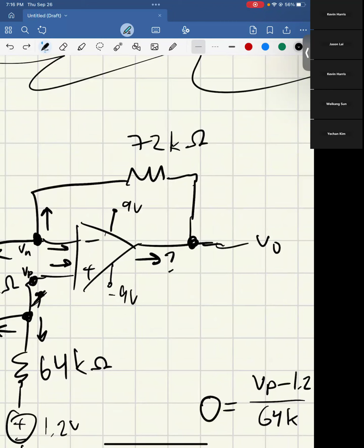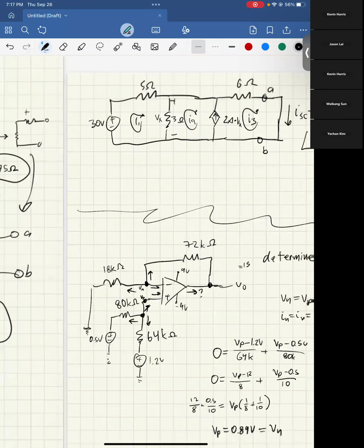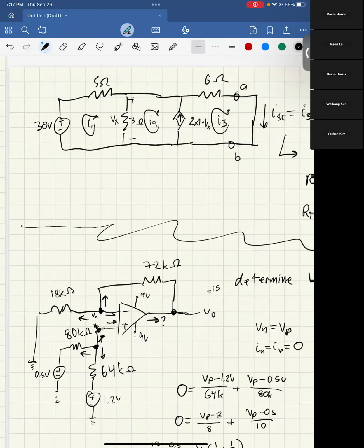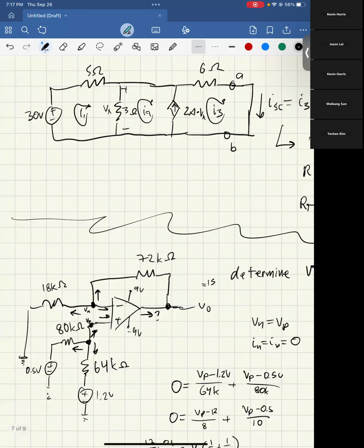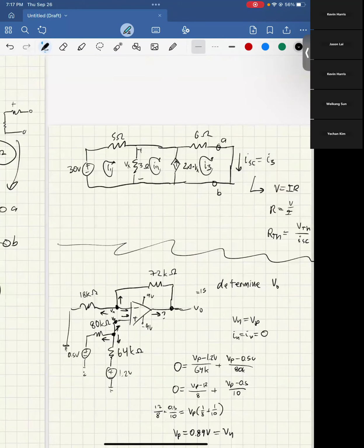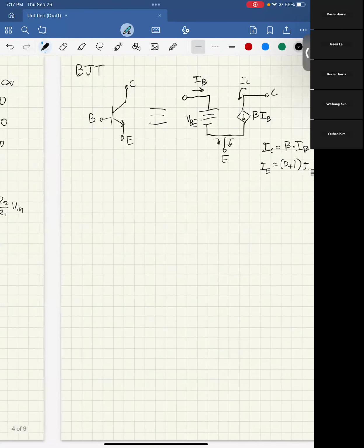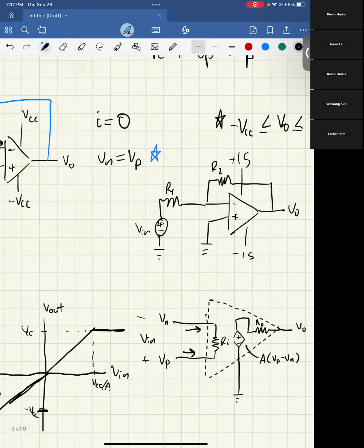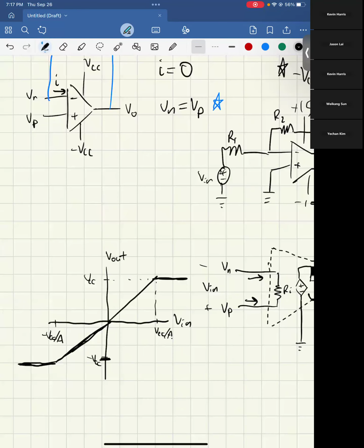So what would happen then is, let's say this was hypothetically 15 volts after you do all of your math, but your input's only plus or minus 9, so it tries to go to 15 volts, but it can't, so your final would end up being 9 volts because it gets clipped to that 9 volts, which is the kind of thing you saw here, where it tracks pretty well.